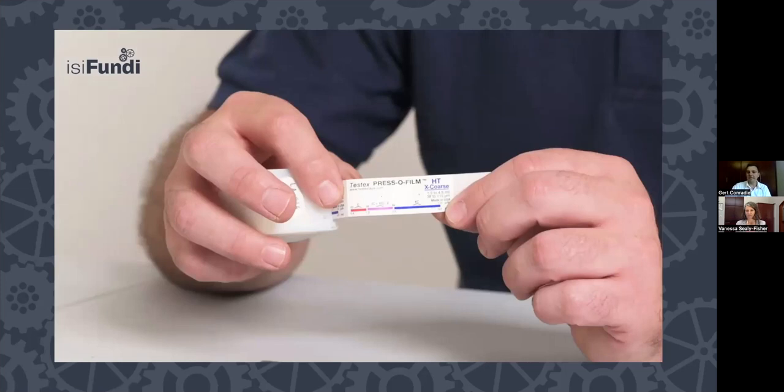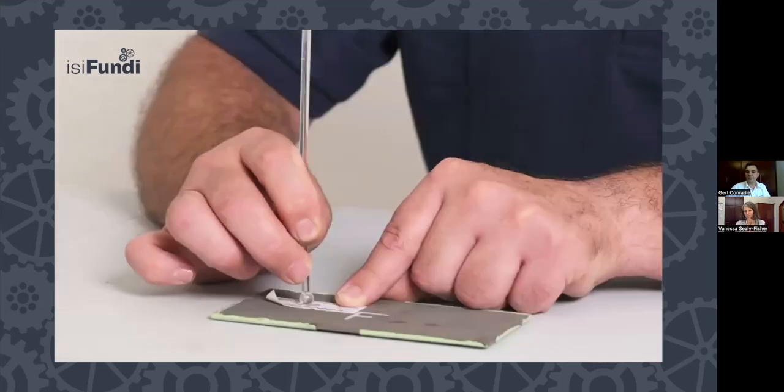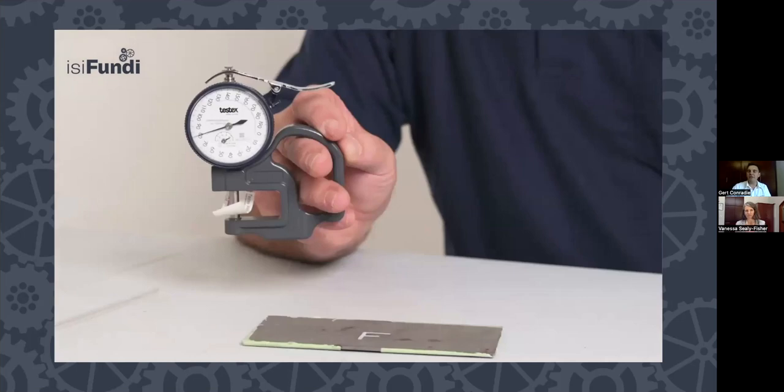And taking this replica tape is almost like an impression that a dentist would do. He puts that putty on top of the thing and shoves it into your mouth, and he tells you, bite down. So now you've bitten down on top of it. And what has he got? He's got an exact replica or imprint of what your teeth look like. And this is exactly what this little piece of tape does. It's a piece of tape that when you actually force it down onto the substrate will form an impression or a negative impression of what the value is of your profile in that area. And then by taking a measurement, you can accurately now measure what the profile is.